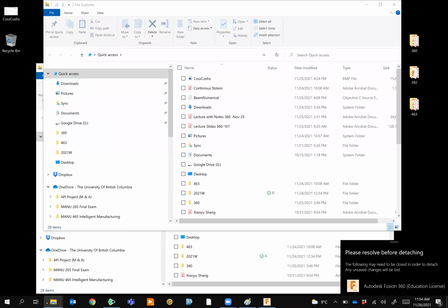Right. So we have these n different mode shapes, and we have these n different natural frequencies. And then you talked about exciting it at a certain natural frequency. So say we take the beam and we excite it at natural frequency omega 3. We're going to expect the oscillations to be of the shape Y3. We are going to expect to see an oscillation which is very close to mode number 3. It doesn't mean that it doesn't have other stuff, but it's going to be dominated by that one.